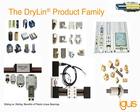Here's an overall comprehensive look at the DryLin product family by igus. So this is our linear bearing specialty line. Starting from the top left, you'll notice a series of round parts. Those are interchangeable with recirculating ball bearings. We also offer aluminum shafting, steel shafting, and stainless shafting, both inch and metric sized. Below that, you'll see DryLin T, which is interchangeable with common profile rails that are on the market, but again uses plastic sliding parts instead of ball bearings.